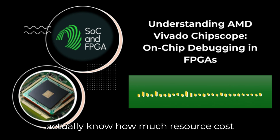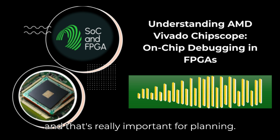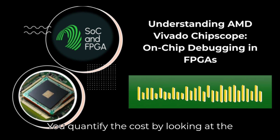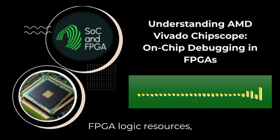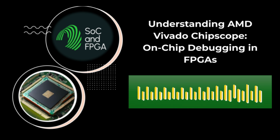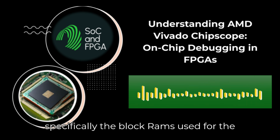How do you actually know how much resource cost you're adding? Can you estimate it? Yes, and that's really important for planning. You quantify the cost by looking at the resource utilization estimates. This is measured primarily by the consumption of FPGA logic resources, LUTs and FFs, and memory resources, specifically the block RAMs used for the trace buffers.